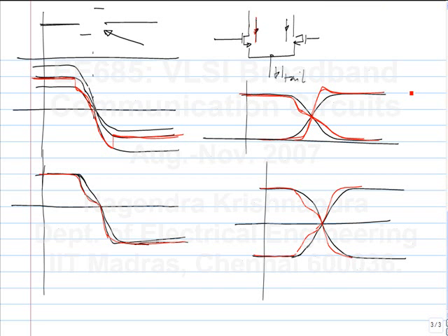Differentially, ideally, it looks like they will cancel out, but in reality, it will also not cancel out very well. And also, in case of an equalizer, you will be summing the outputs of many taps, all of which have different weights. Some of them will be rising, some of them will be falling. So you will be summing a whole number of things, and the result may or may not be linearly related to the input, depending on the weights. But if you look at the single-ended waveforms, they will definitely be non-linearly related, because this is the response to a negative step and this is the response to a positive step, and they don't look anything like each other. So you can't really use that if you apply a sine wave, but in this case we are not using it.